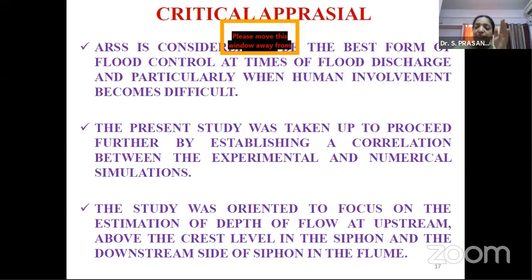For that spillway, we have evaluated the dynamic pressure, velocity magnitude, the depth of flow in the bucket, the trajectory of the jet going downstream of the spillway, the crest level on the top, and how the dynamic pressure varies throughout the profile of the spillway. Each application gives you a different parameter.